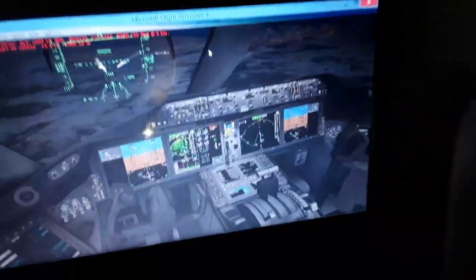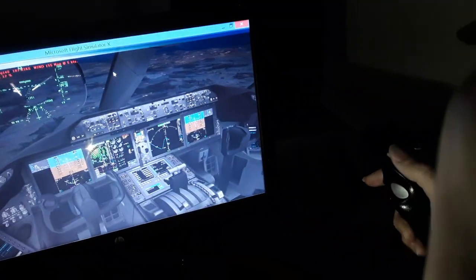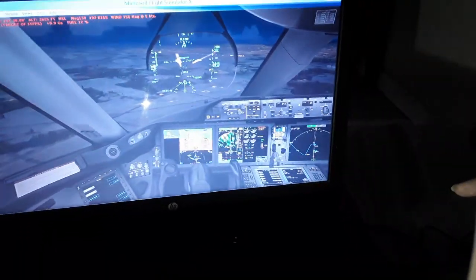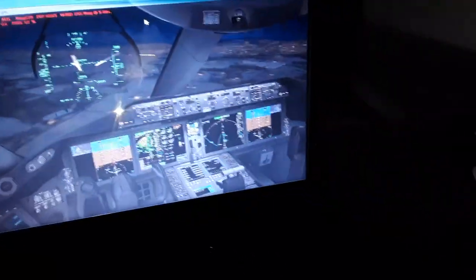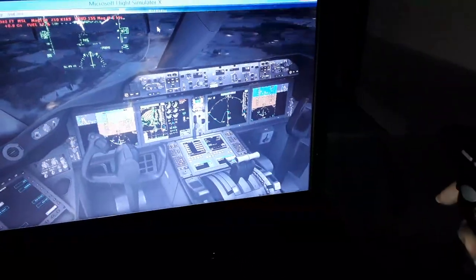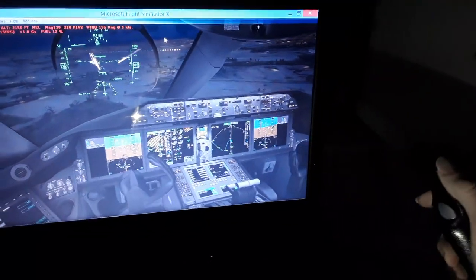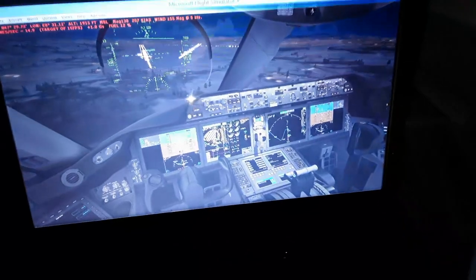So you can see, I just showed you the LSZH localizer, how we follow. You can see we have some side wind gust. We need to grab the aircraft a little bit. A bit more idle for approach and landing. Increase the rate of descent over here. Keep flying manually.